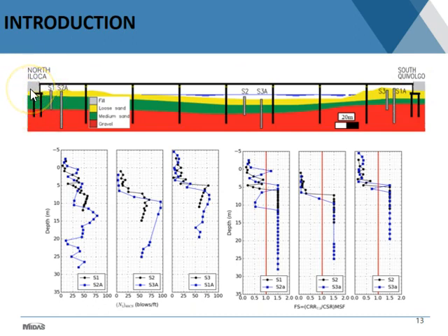And in the case of the abutments, because we're going to focus our attention on the abutments, each one of them is supported by 2 rows of 4 drill shafts having a circular cross section. Okay, here you see the 2 rows, and every row has 4 piles, and these were reinforced concrete drill shafts, and they were rather long, I would say. I mean, compared to some other designs that we have seen in our country.